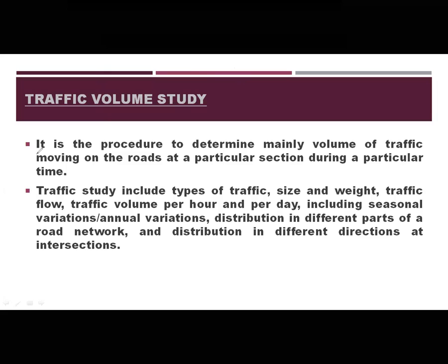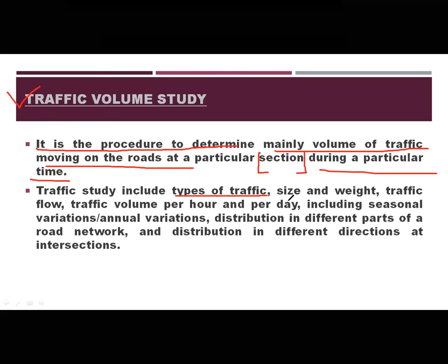So collecting this data, or the procedure to determine the volume of traffic moving on a particular road section during a particular time, is known as a traffic volume study. A traffic study includes collecting data related to the type of traffic, size and weight, traffic flow, traffic volume per hour, per day, including seasonal variation, annual variation, distribution, different parts, networking, etc.